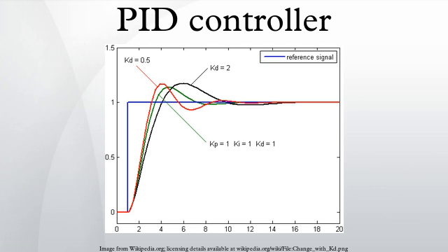The other controller acts as inner loop controller, which reads the output of outer loop controller as setpoint, usually controlling a more rapid changing parameter, flow rate or acceleration. It can be mathematically proven that the working frequency of the controller is increased and the time constant of the object is reduced by using cascaded PID controllers.